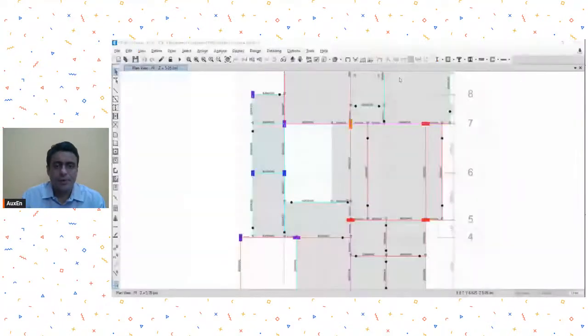Okay, how do I put it? I'll just again show you. You go to response spectrum function, define, and you go to response spectrum function over here, and then you define this. Maybe you can define it as user defined function. Let's name it as AV.